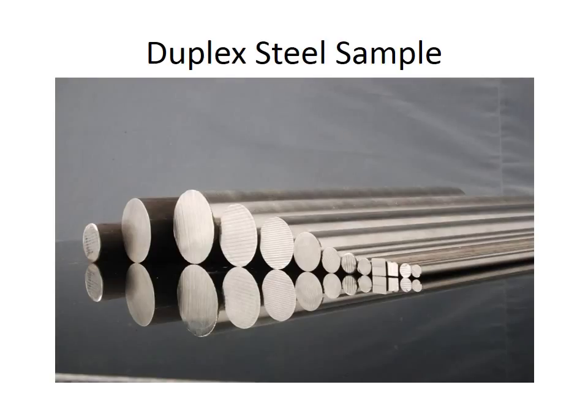Now enter duplex stainless steel. This steel offers excellent resistance to corrosion and has a very high mechanical strength. The high corrosion resistance of duplex stainless steels ensures significantly more uptime than carbon steels and conventional stainless steels, while the mechanical strength allows for lighter constructions, more compact system design, and less welding.